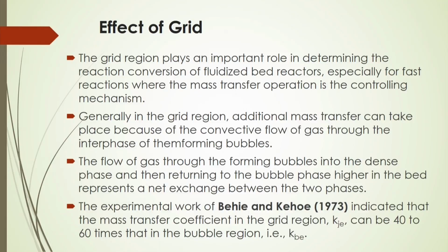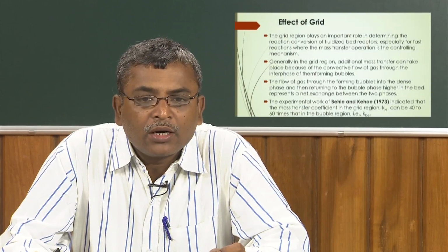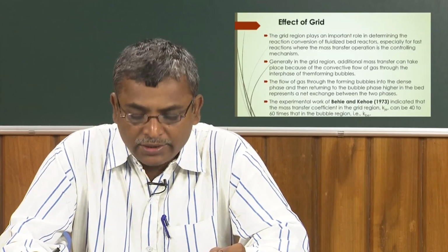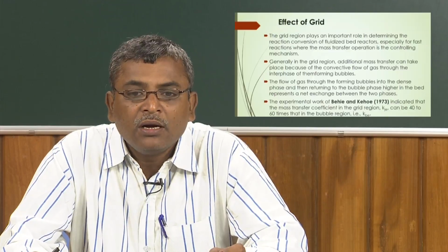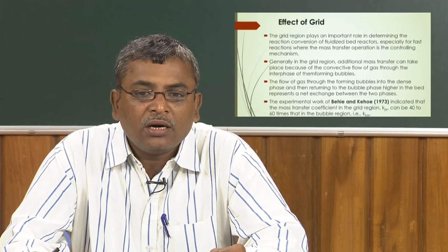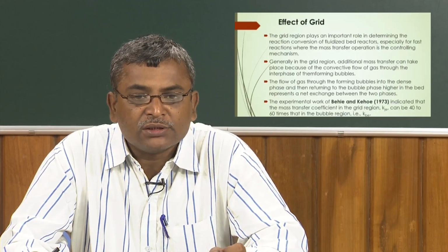And the effect of the grid: is there any grid effect on the mass transfer or not? The grid region plays an important role in determining the reaction conversion of fluidized bed reactors, especially for fast reactions where mass transfer is the main controlling mechanism.